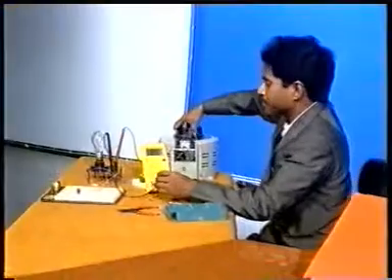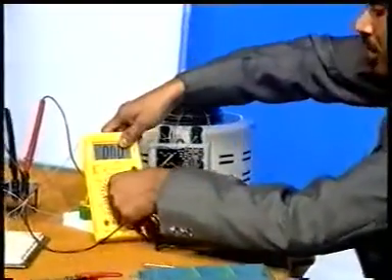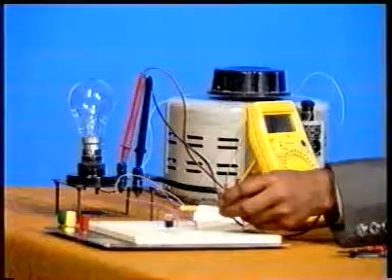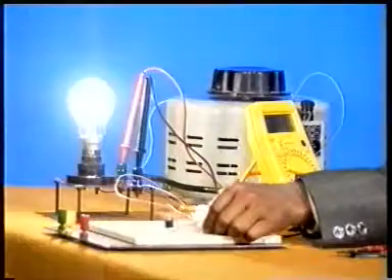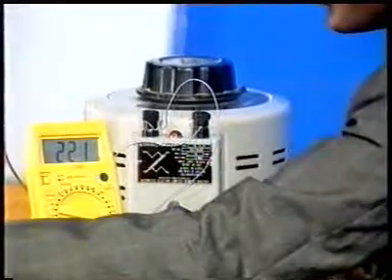Again give the same voltage, that is 200 volts, and change it to AC because it will give you AC output. Now he is going to give the pulse at the gate, and you see in this case the illumination is much more and the multimeter is also showing about 221 volts. So in this experiment we have verified two things. Number one is we have seen the health of two components, that is SCR and Triac, and both were found healthy. The second thing we saw was the distinction between the SCR and the Triac.